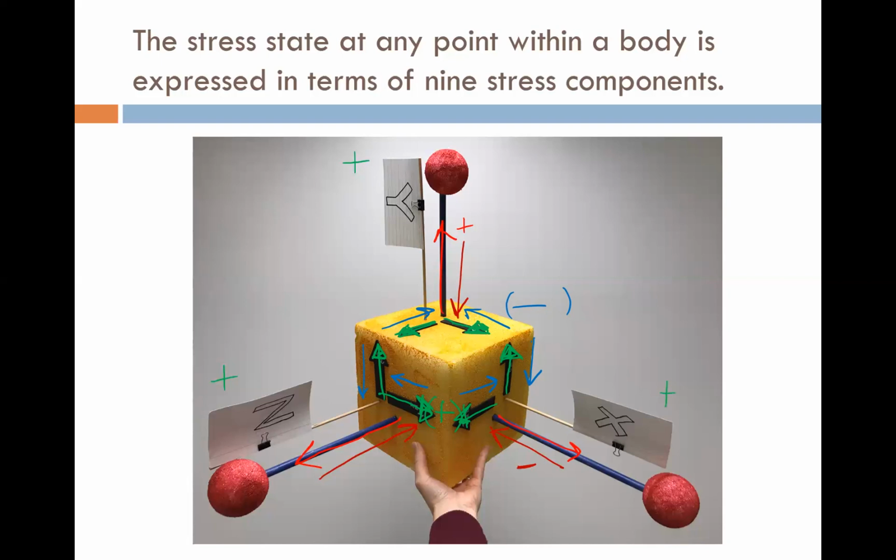And that's really also true of the normal stresses, except that it's much easier just to think: if I'm going outward from the cube, I'm positive, and inward, I'm negative. Positive sign convention: positive direction on a positive face, and negative direction on a negative face. If you ever have a combination of the two, say a positive direction but a negative face, that's when you get negative sign convention. So it's just like multiplication. Multiply two positive numbers or two negative numbers and you get a positive. But if you multiply one negative and one positive, you get a negative.